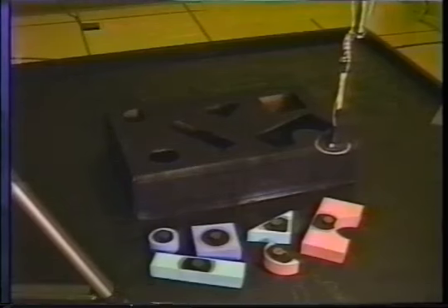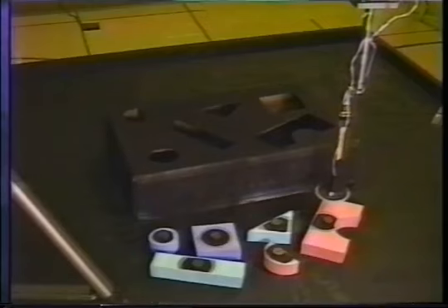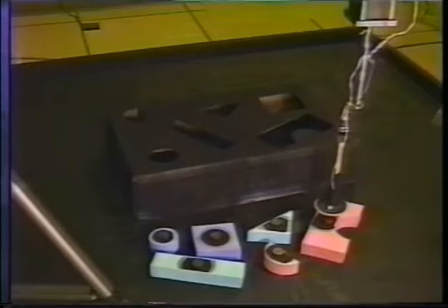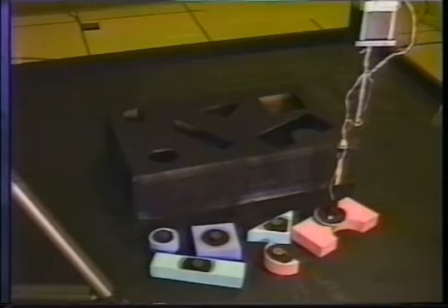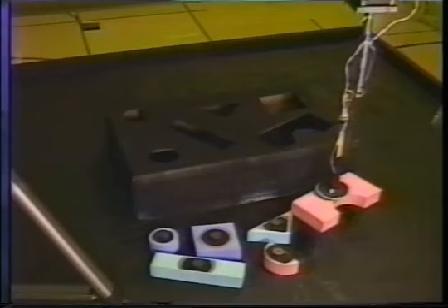For the translations, the first 3 arm joints are used, while for the fine manipulations both the arm and wrist are moved. Thus, a simpler 3-degree of freedom model is estimated for most movements. The full model only needs to be learned near the insertion point.